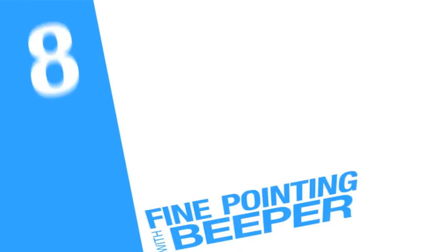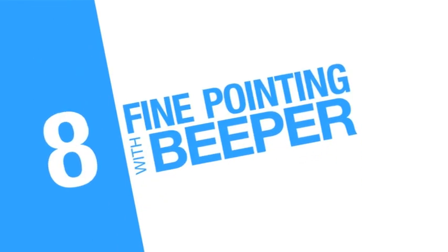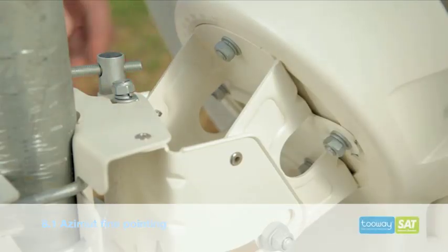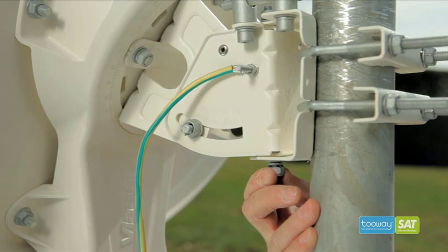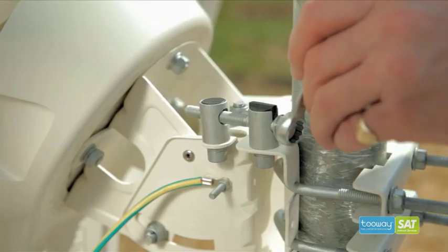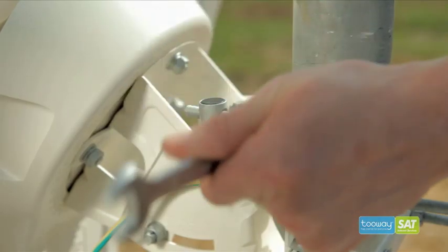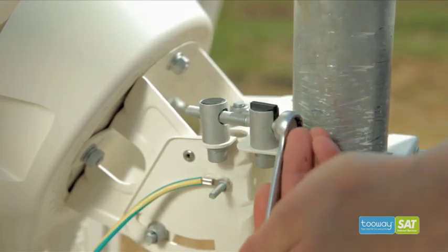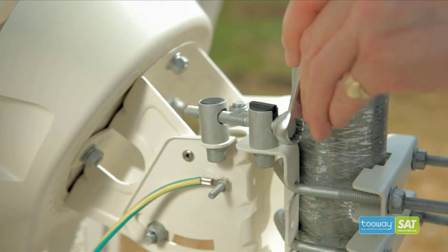The fine pointing of the antenna is the same procedure whether you found the satellite with either the KU pointing tool or the beeper and inclinometer. The first stage is the azimuth fine adjust. You verify that the two azimuth locking nuts are loose. You must pass the maximum signal level in both directions to allow the modem to measure the maximum signal-to-noise ratio.